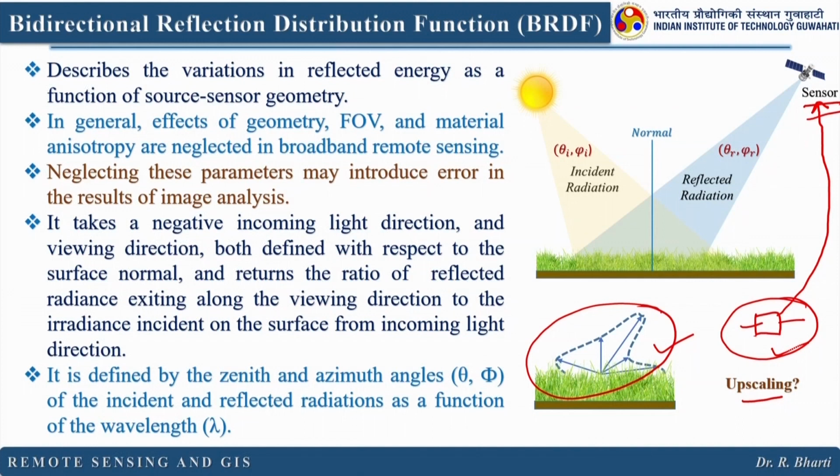So, what will happen? You may have access to this particular area, but you cannot access this whole area, right. So, what you will do? You will characterize this particular area, and then you will establish a relationship to resolve this whole area, right. So, this is the advantage with remote sensing, that you do not have to go to all the places, but you have to calibrate or you have to produce the accuracy with respect to your ground information, right. So, here this BRDF concept is very useful.